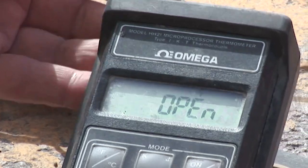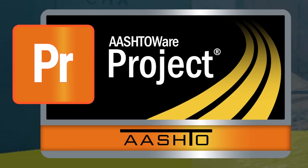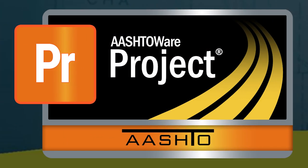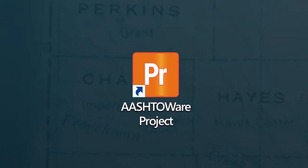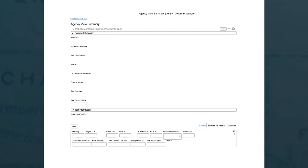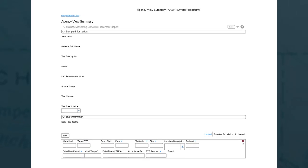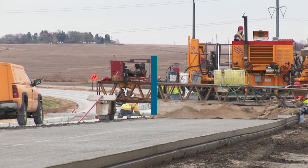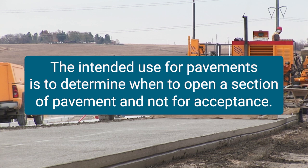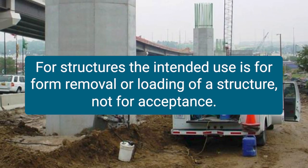Data acquired for determining the opening and acceptance of concrete placements shall be recorded into the AASHTOWare project software. The Nebraska Department of Transportation requires that field personnel be responsible for maintaining electronic documentation in AASHTOWare project. The agency view is used to enter the required data for mainline pavements, structures, and pavement repair applications. The intended use for pavements is to determine when to open a section of pavement and not for acceptance. For structures, the intended use is for form removal or the loading of a structure, not for acceptance.